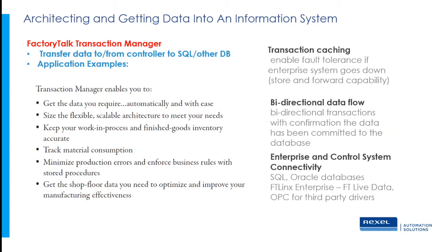It does have transaction caching, which is nice. It enables fault tolerance, so if your database goes down, it stores the data locally and will store and forward when your database comes back up. It's bidirectional, so you can send data to the database and read from the database. It has enterprise connectivity: SQL, Oracle databases, FactoryTalk live data, or any OPC data for third party. So that might be a good reason, if you have other third party controllers you need to log into SQL, Transaction Manager will get the job done for you.